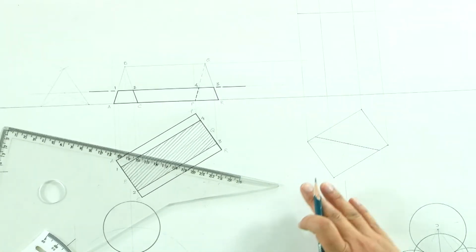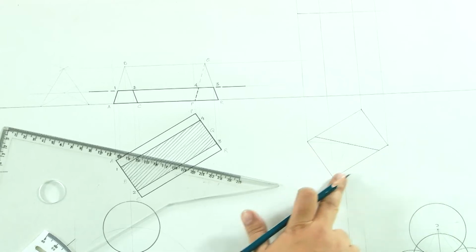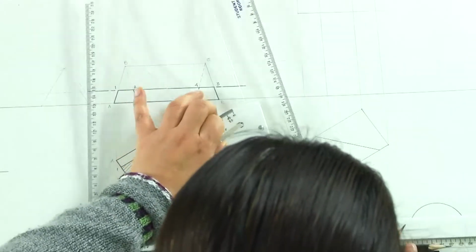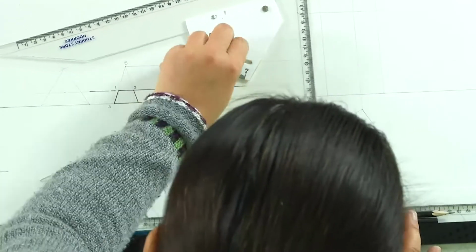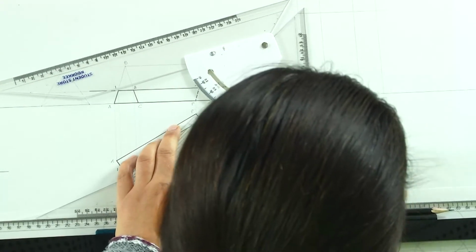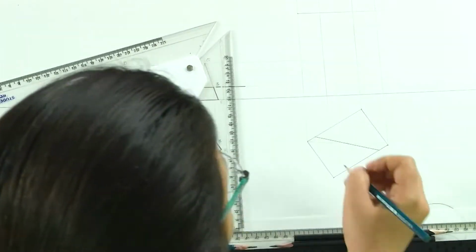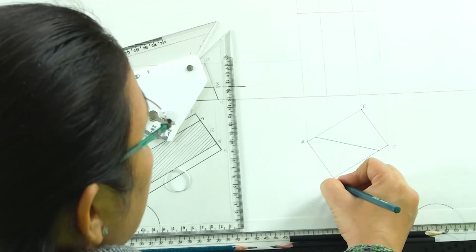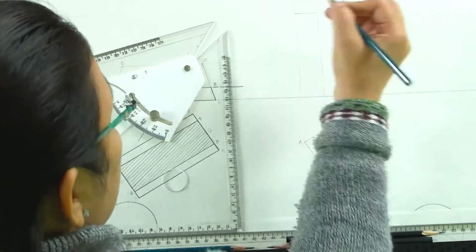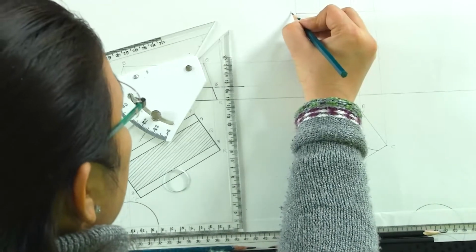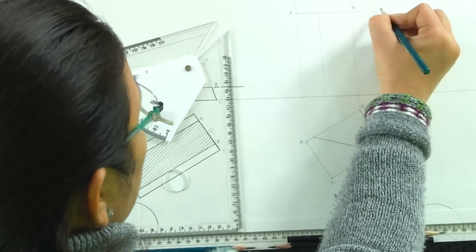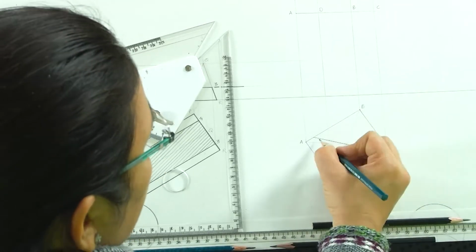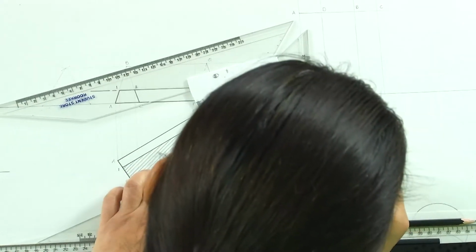So, we are assuming that this portion is now cut out of this solid. Let us take the projections back where this section line is cutting. So, let us number it for our convenience. If this is A, B, C, D, I am only marking the top face, and this is A, B, C and D. Now, this AB is cut in this point.